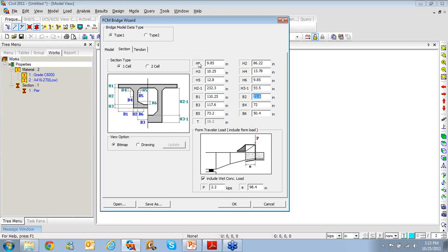If you're using type 2, then you can even bring in your sections from the CAD drawings, create them in the section property calculator, and then create the section from it and bring it here. I would recommend that approach only if your segments are not the common sections, and there's some unique shape involved there. Otherwise this is a lot easier approach.